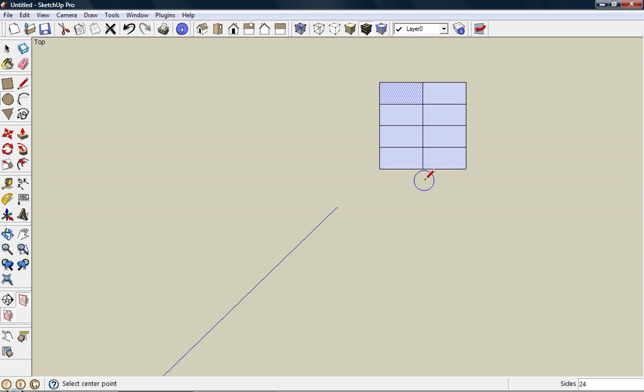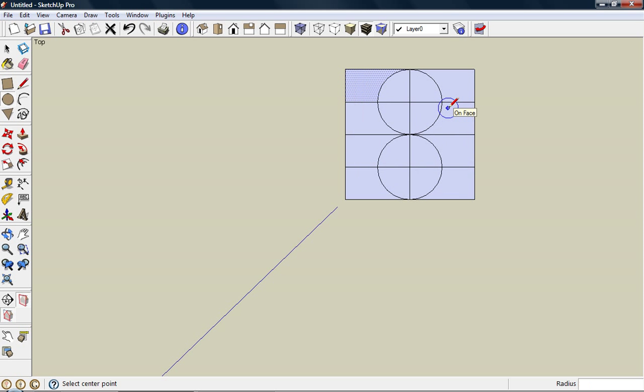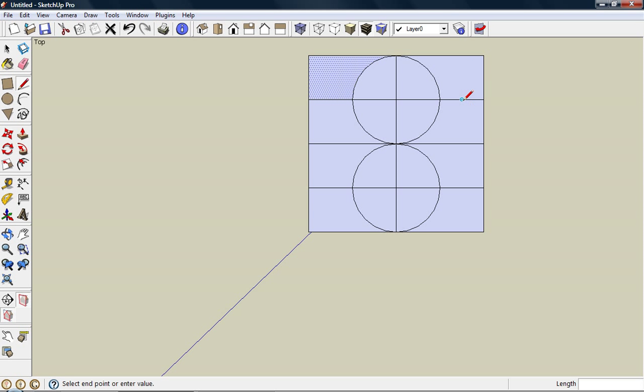I can use these new snapping points to draw additional lines, which will again redivide those lines. Now if we use some of the other tools in combination, we can start to create more complex shapes. So I've just snapped my center onto that endpoint, and instead of entering my radius in the measurement toolbar, I'll snap to this endpoint. You'll see in the measurement toolbar down there under radius, it's set at 3/4 of an inch. That was set just by snapping onto that endpoint. I'll do another circle, and we'll grab the line tool, snap to a midpoint here, move up in the green direction, and last I'll select an arc tool,